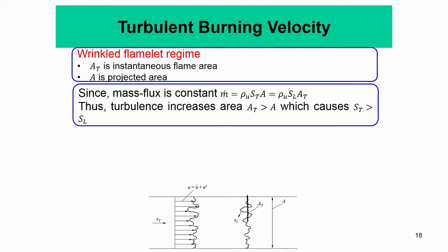That means it is fluctuating about this constant line, or area A. So for this, if you remember, for a laminar flame to be stabilized or stationary at a particular location, the reactants must enter it at a velocity given by the planar laminar flame speed SL.